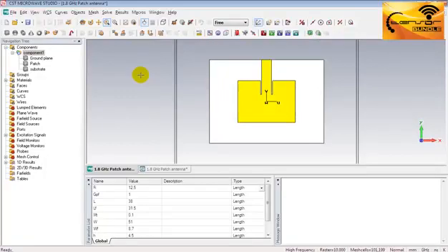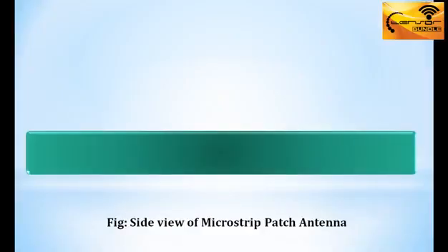The size of a port is an important issue because large-sized ports will allow higher-order waveguide modes to propagate in the port. And the important thing to remember is that I have used a microstrip transmission line to feed the antenna. And whenever a microstrip line is used to feed the antenna, a basic rule regarding port size must be followed. Look at this figure to understand the concept.